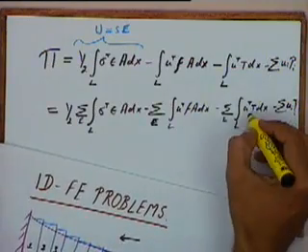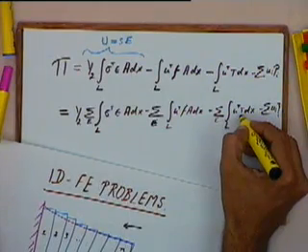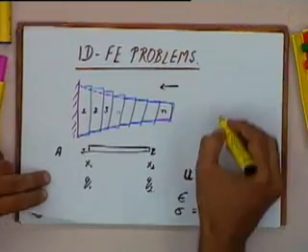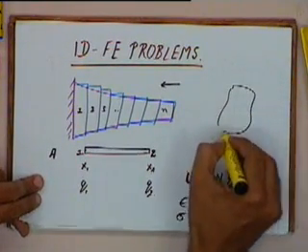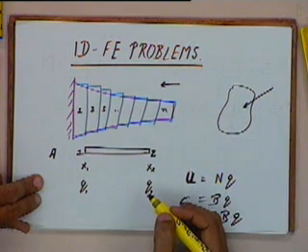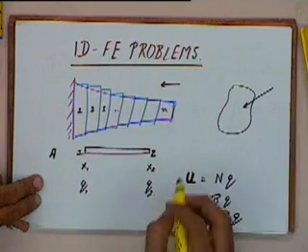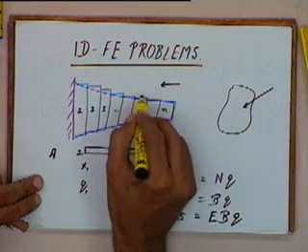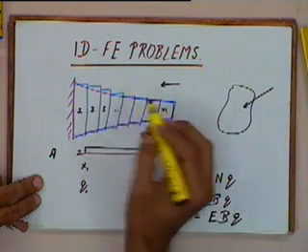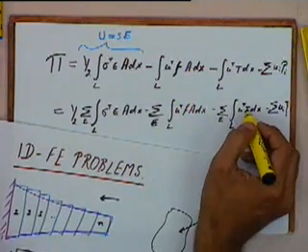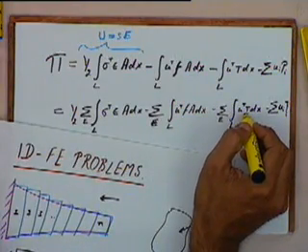So in this case this T that I have used is force per unit length, and this is a one dimensional case. If it is a three dimensional case, if I have a three dimensional surface patch like this, I can have a force acting on a per unit area basis. That is a force acting on the surface, but that is a 3-dimensional force. But now I have a 1-dimensional force acting along the length. So I can effectively take that to be force on a per unit length basis. So this tractive force is a force per unit length and not per unit area. That is why that length term is not visible.